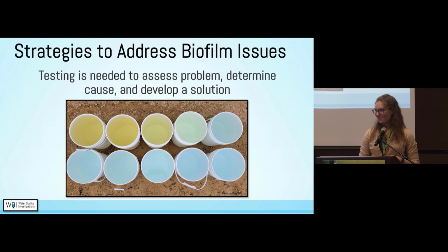We have 5-gallon pails that are white, and we basically line them up next to the raw water tap, and we don't want treated water at this point, so that's why it's well water. And after the well has been not running for a certain period of time, we'll then create water demand so that the pump is running continuously. And then we'll fill up a bucket every minute of pumping, basically. So this would represent 10 minutes of pumping.